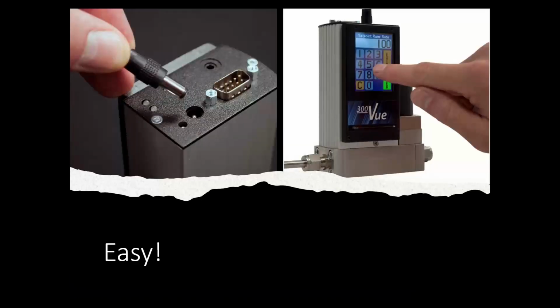Or if you want the easiest of all, you can go with the 300 Series line of flow meters and flow controllers. And these can be powered by simply plugging in a 24-volt power supply, as shown there on the left. And with a touchscreen display, you enter the flow rate, and the MFC takes care of the rest. And I'll also mention that all Digital 300 have both analog and digital I/O. So you see the top cover there shown on the left.